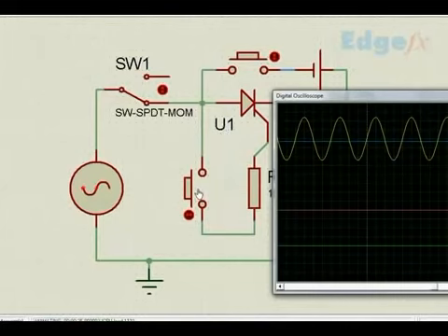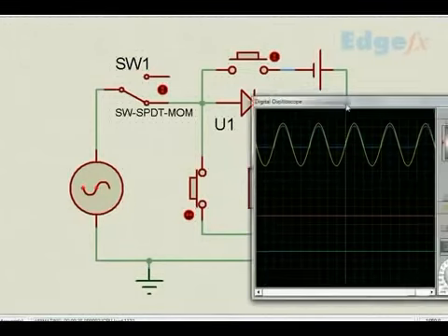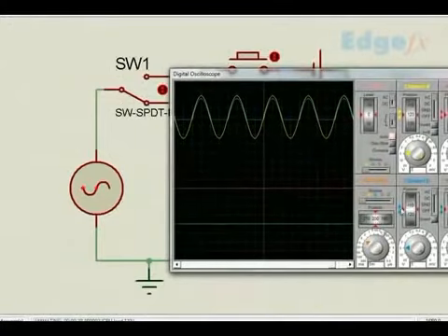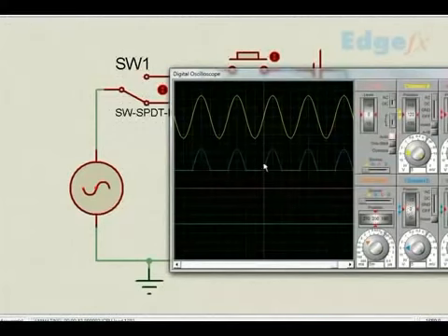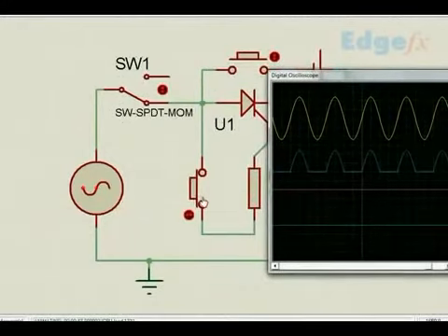So when I trigger this, or when I pass the current through the gate to cathode, or I keep it pressed, you see this blue line which you find here is the half wave which is going. If you would like to see it better, we can even put it down. I can see this is my half wave which I am getting, because I have triggered it permanently. That means every time a pulse is coming, the current is flowing between gate and cathode.